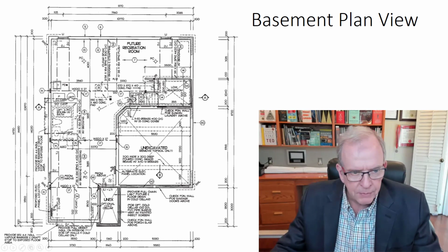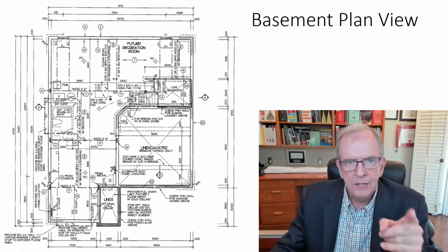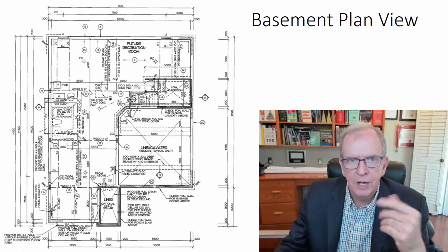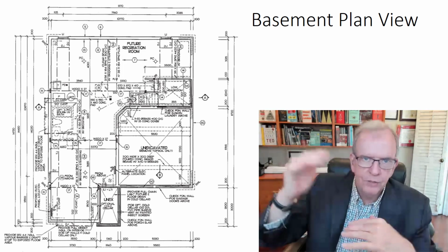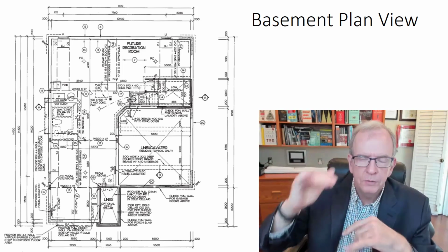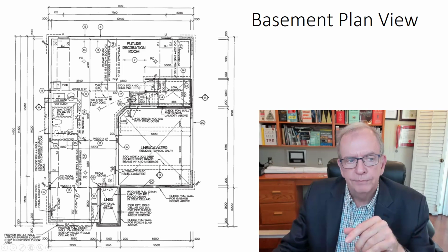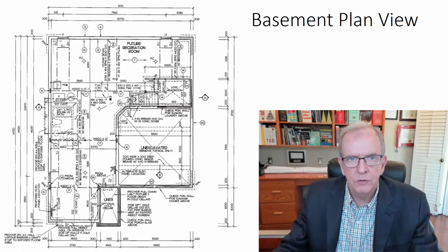So of course the steel beam is running through, and I know it's a steel beam because it says it's a W200 by 27. If you're working with Imperial, it might say a W8 by, I don't know, 15. That just means the W means wide flange I-beam, which is a typical construction I-beam. It's 8 inches high or 200 millimeters, depending how your beams are being made, out of Imperial or metric measurement. They're slightly different. And the weight: this is the weight per meter, 27 kilograms per meter, or if it's imperial, it would be pounds per foot.